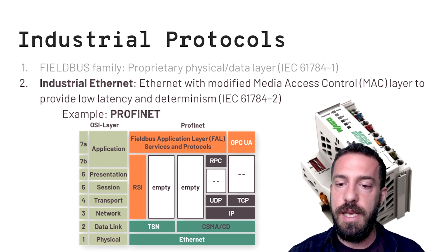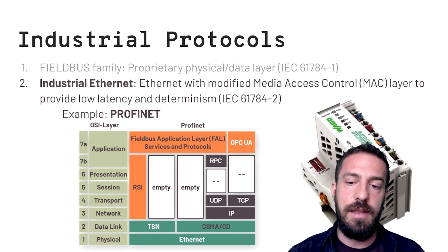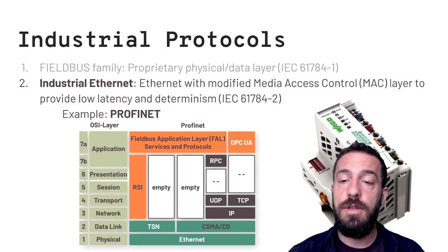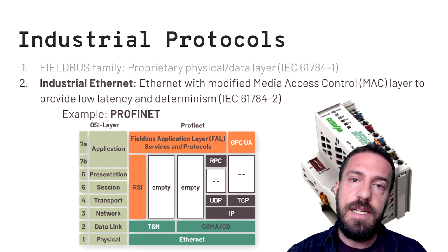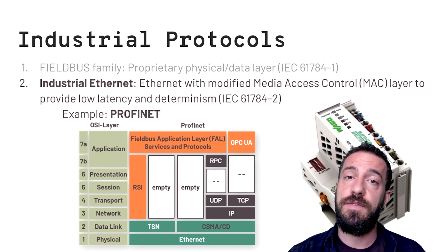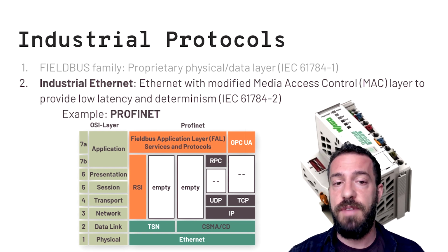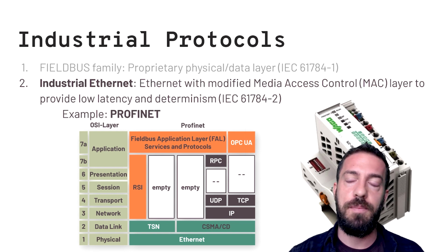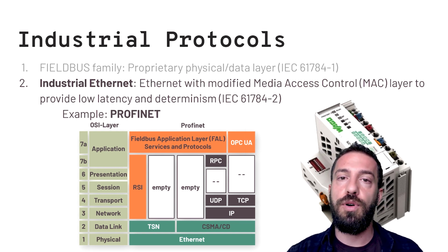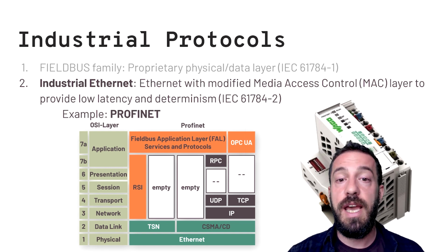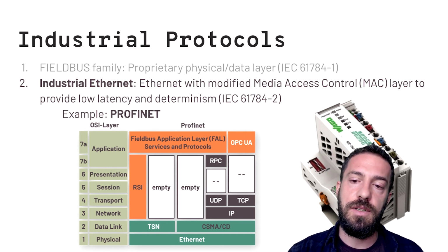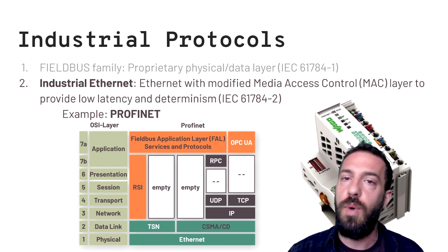Instead of proprietary, this is your standard Ethernet, and you use a standard Ethernet cable to connect to that. So you can understand this is good because you can connect PLCs from different vendors, because they all support a unified protocol. And also to be able to talk to many different PLCs, you can use standard Ethernet switches or gateways to scale up your network to any number.